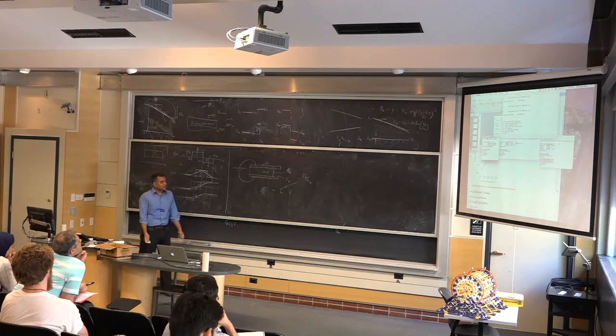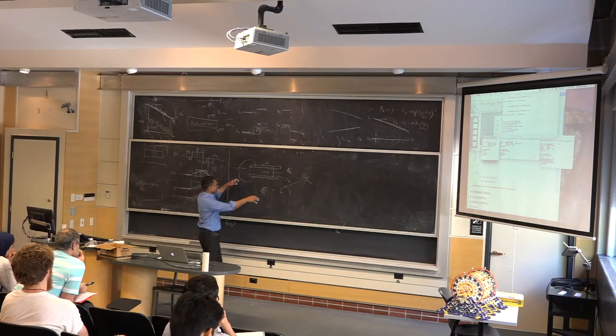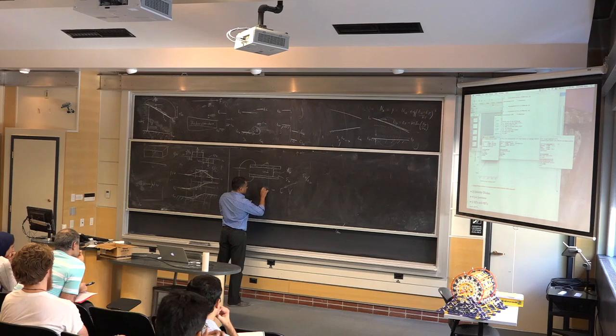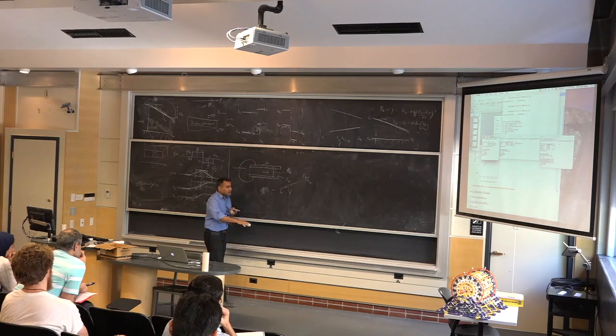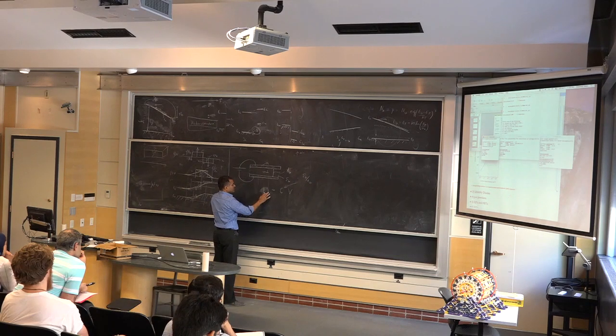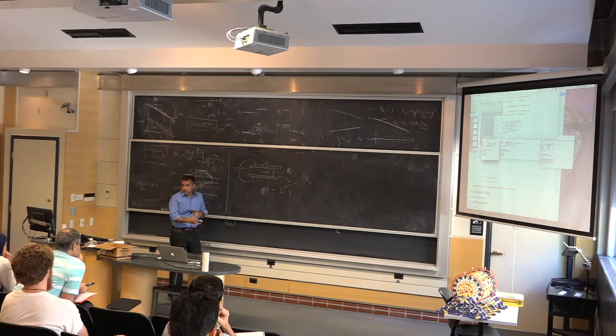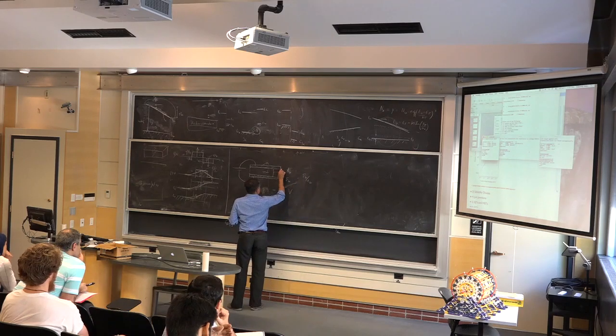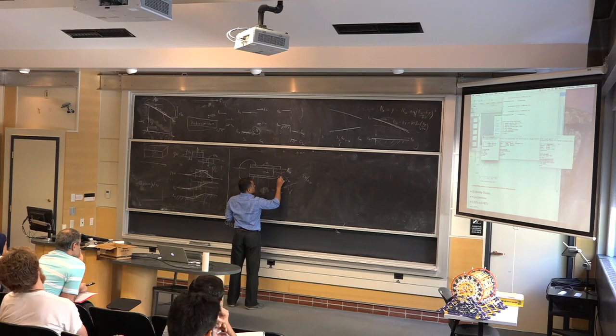There's nothing else. I mean, this is the answer to it, right? There'll be some details of fringing fields and all that. We're not bothering about that right now. So the charge density, instead of writing it sigma, you can write it as Q times a sheet density of electrons in the metal. The metal can be very thick, but where will those electrons be? They will actually be on the surface, meaning electrons here and positive charges here. Make sense? Equal and opposite. If you draw the microscopic picture of it, let's say the voltage is positive here. What you have is a positive sheet charge here and a negative sheet charge there.